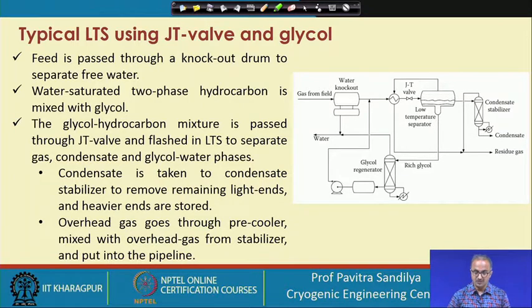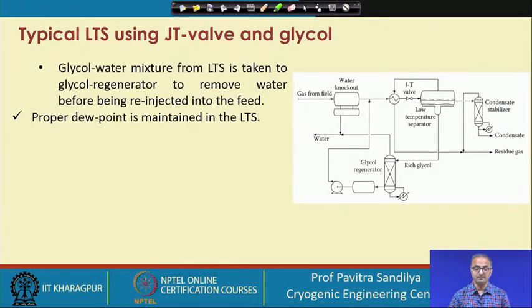Okay. So, this is how this system is working, and we have to keep the proper dew point in the LTS system to maintain the amount of the heavier gas component, because we know that the dew point dictates the temperature at which the condensation will start taking place.